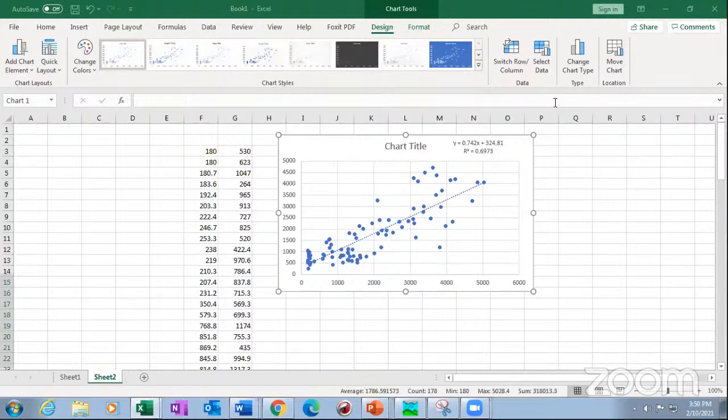Model is auto-calibrated and fine-tuned by manual calibration. Is that right? Yeah, of course, that will be okay. I saw earlier that the lag time was around 4,000. In fact, it cannot be more than 300 or 400 minutes for that particular area. In that sense, this is totally a wrong value. That's not a practical value. That's why you have to apply manual intuition to those particular values.